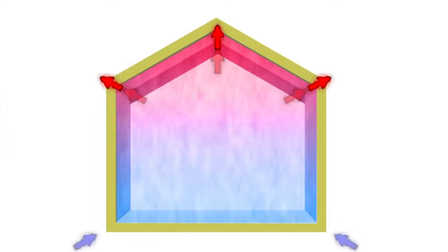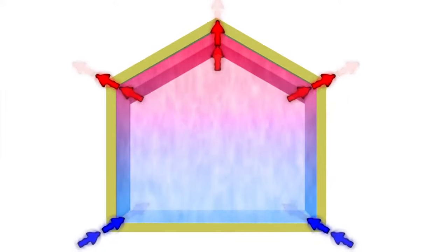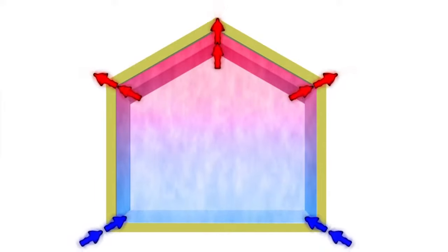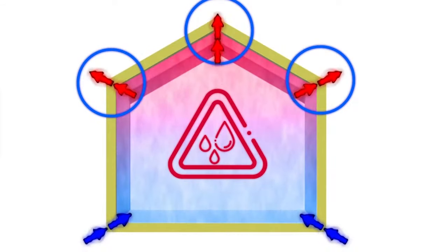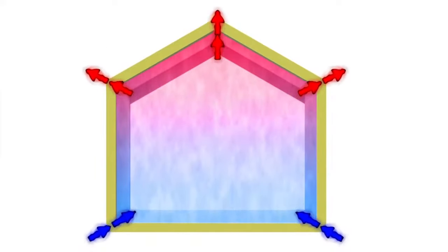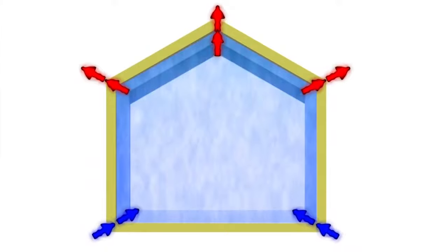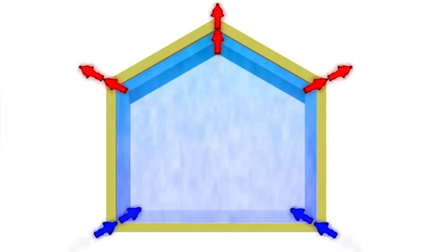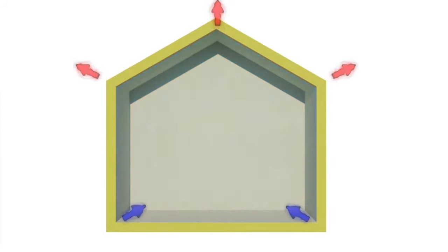Because warm air is less dense, it will rise upwards in a building and can leak out of any air pathways found at higher levels. Correspondingly, as this air rises, colder air must be drawn into the building lower down. As the warmer air will contain significantly more moisture, this outward air leakage can lead to condensation issues as the leaking air cools and deposits liquid water. The cooler air entering the structure lower down will lower the internal temperature in the building, necessitating energy input to maintain the temperature of the habitable space.